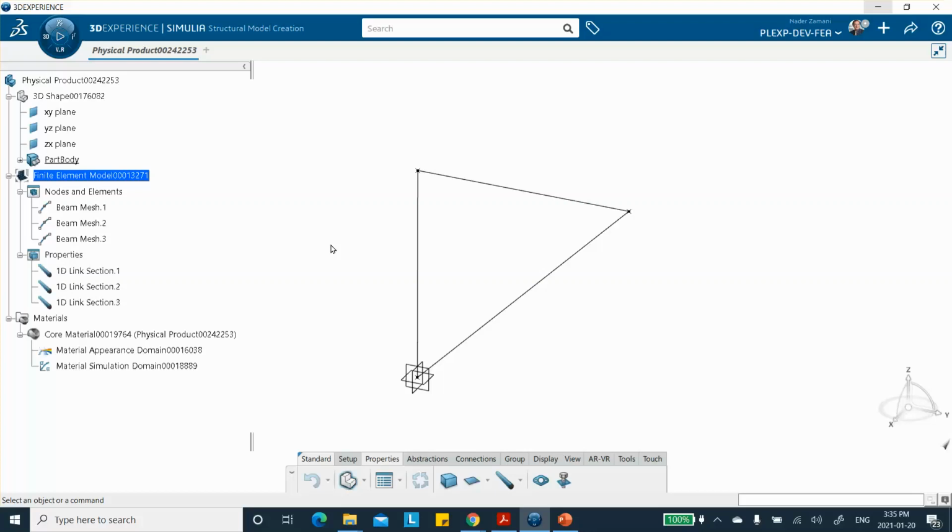All right, so the one thing you want to do, and this is very important, remember I created 4 points here, hide them. Because with some software, when you apply a load or restraint to a point, they don't know that it is actually intended to be on the vertex, and they may not draw.